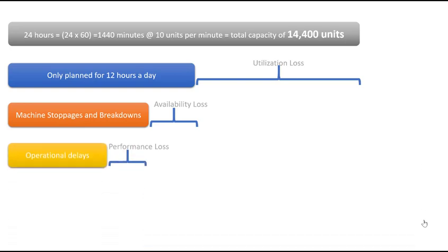The third category is productivity loss. These are small stops and starts, running the machines lower, starting late after the breaks, products jamming for a few seconds, minor setups to get the machine going, and delays caused by the operations team. This category is largely a function of competent shop floor supervision team and a competent and motivated operations team, i.e. on time after lunch breaks. This loss costs the same as the availability loss in the sense that all labor resources plus overheads are paid for in full and yet there is no production.